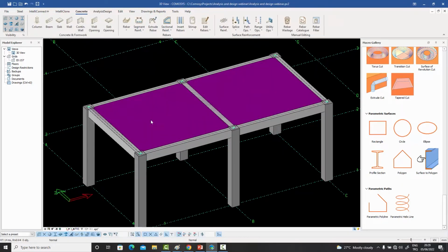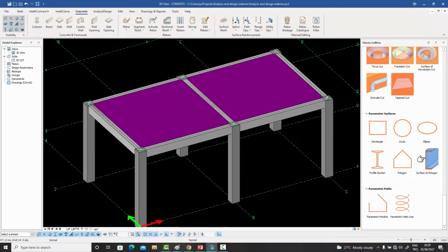Now, these supershells have some really amazing features which really make your life easy when it comes to the analysis of shells. And one of them is its ability to sniff out or locate whenever there's a frame element touching it. So I already talked about how these will be meshed because the supershell is in contact with it.